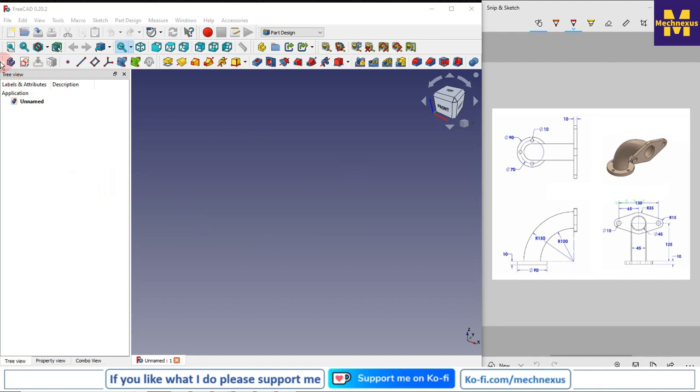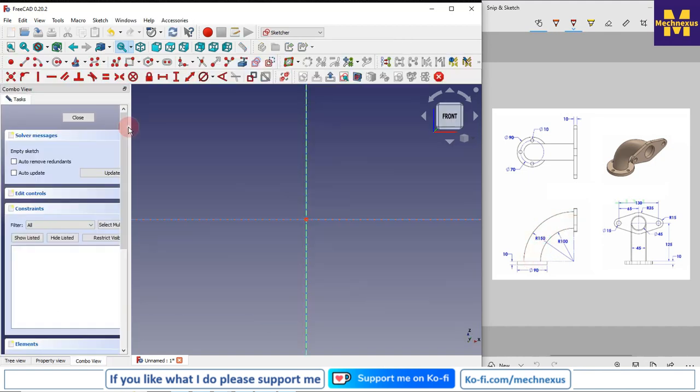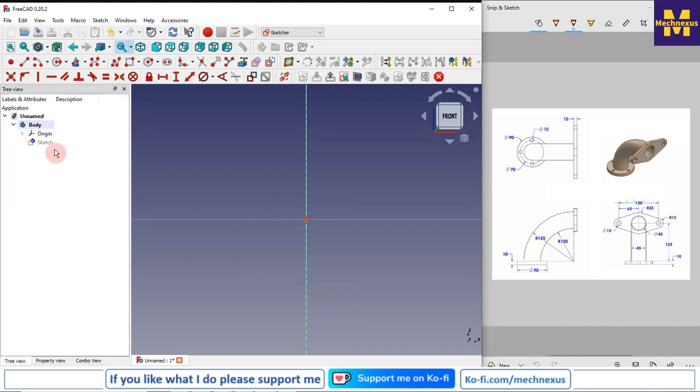So I have created a new file. Now I will insert a body, and I will on my origin plane, and I will switch to the orthographic view, and now I will select XZ plane to make my swept profile. I will create a sketch, and then I will go to the tree view, and I will off the origin plane.